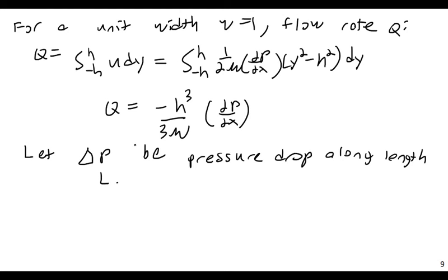So when I say a pressure gradient, this delta p, this dp dx, or this partial of p with respect to x, what do I mean by this? What I'm saying is, as you go along the length of a pipe, the energy in that pipe will go down. The pressure energy, the velocity energy, whatever you want to describe it, the energy in that pipe will go down. We have discussed this before when we've labeled the concept of head losses, but this is the first time we're actually seeing how you might directly calculate it. And it comes directly from the Navier-Stokes equations, from these base principles.